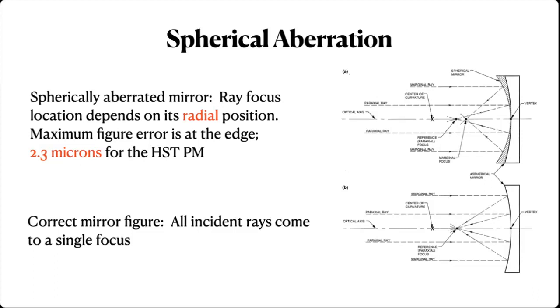I had heard somewhere, I thought, that they were diamond turned. The blanks were diamond turned, but the final polishing could not be done by diamond turning for these types of wavelengths, because diamond turning will generally leave a surface ripple at some tiny scale. And for something like that, I would expect it would have shown up over the entire aperture. So you must have post-polished that. Oh, correct. Absolutely. Thank you. Thanks, Jeff. You're welcome, Bob.